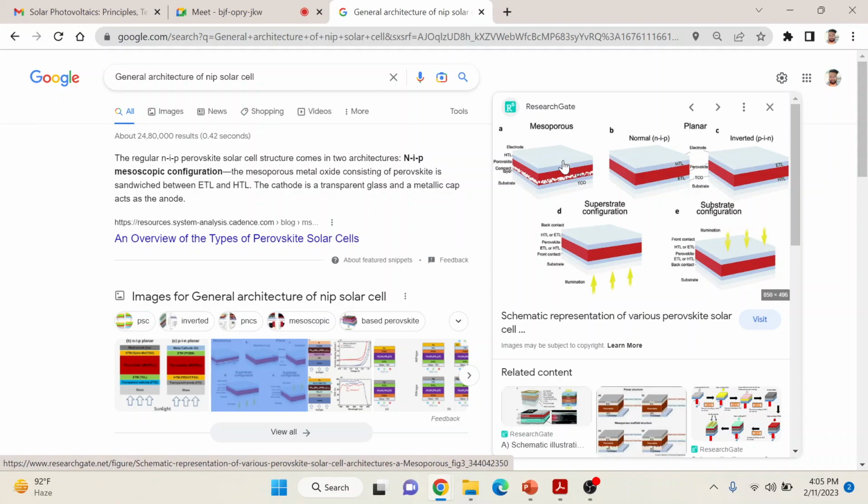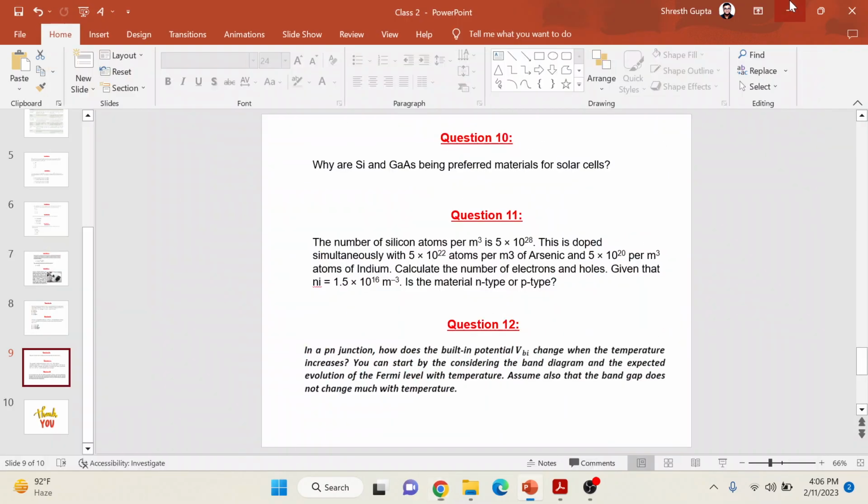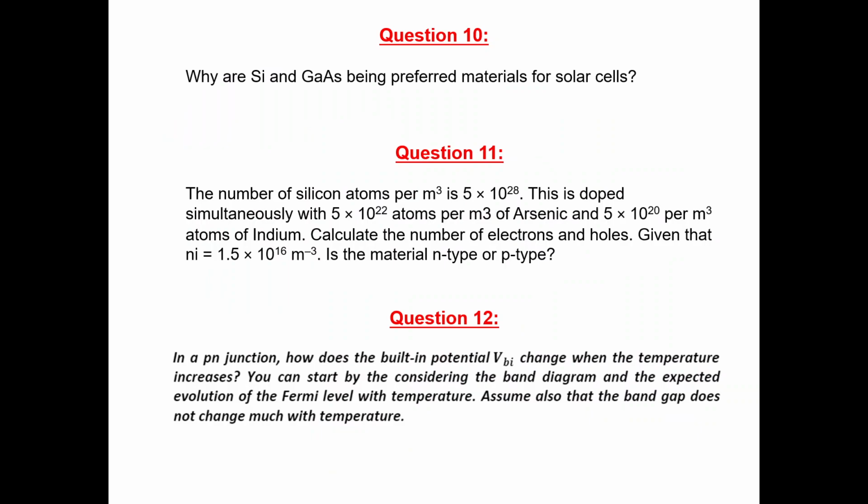In order to choose this material, I put in this question that the band gap should satisfy a particular condition, and that condition is not the only condition that should be taken into account. We should also worry about the absorption coefficient and other factors. So not every material which has a lesser band gap or high absorption coefficient will be good for use as a solar cell. And solar cells are different from LEDs and other devices. It's just for increasing your knowledge.